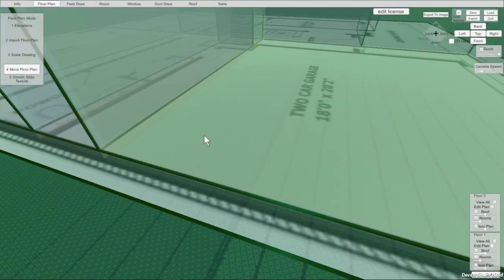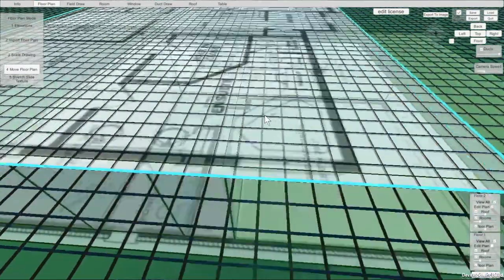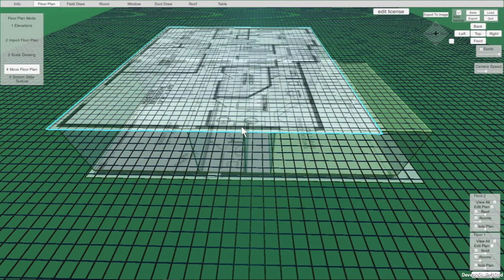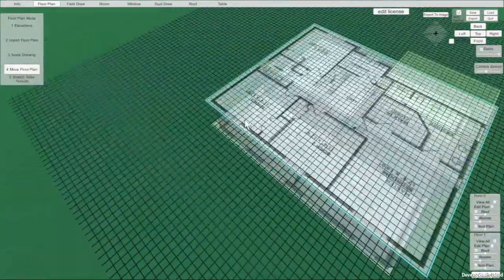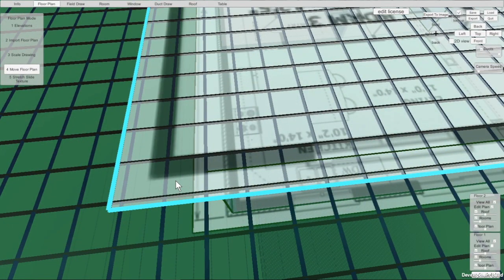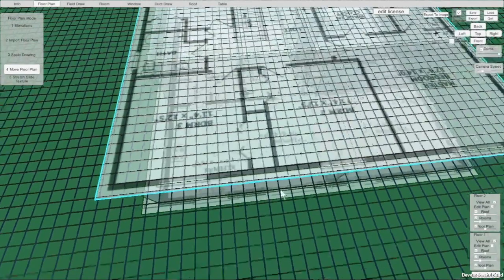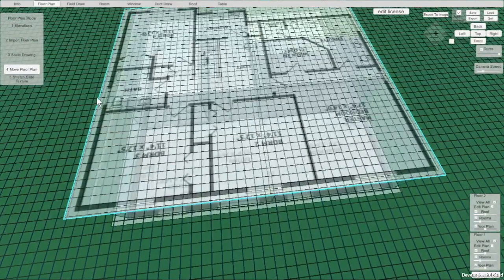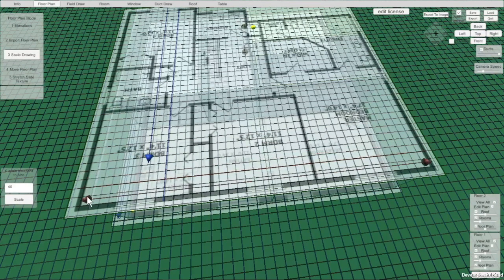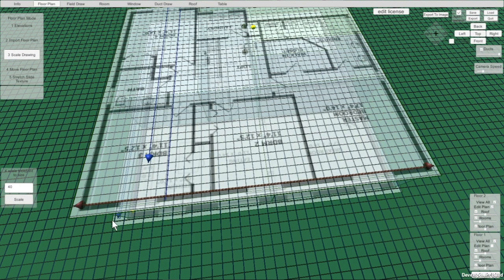And then you can go over and check the other side. If the other side's off a little bit, and that's very possible, you can adjust it. So let's look down here and go, yep, sure enough, it's off by a little bit. So we did that as 40 feet, so let's redo this top one. For some reason it's off just a tad. So we'll do scale drawing, come back here, there, maybe a little longer, a little bit longer. There we go.